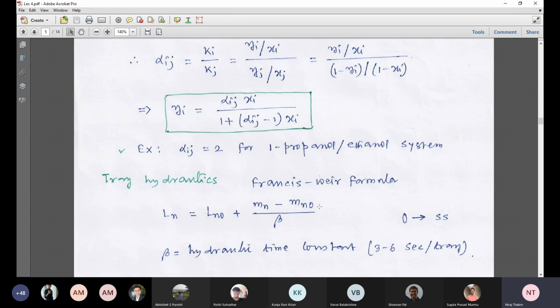So we can calculate the volume of the tray, pi r square h. Now 20% of this volume is going to the downcomer section. That means 80% of the volume is basically dedicated to holding the liquid. So volume is known, this is volumetric holdup, we can tell.